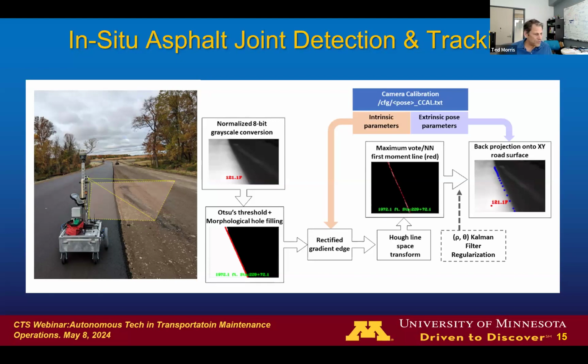This is all done with some very relatively basic computer vision steps with the limited data. This is one way to do it. This is a very efficient algorithm that can run on very simple, low-cost processors. And the idea is you then just localize an estimate of the center line using the IR camera to differentiate temperature, because newer pavement is a lot warmer than pavement that was laid before it.